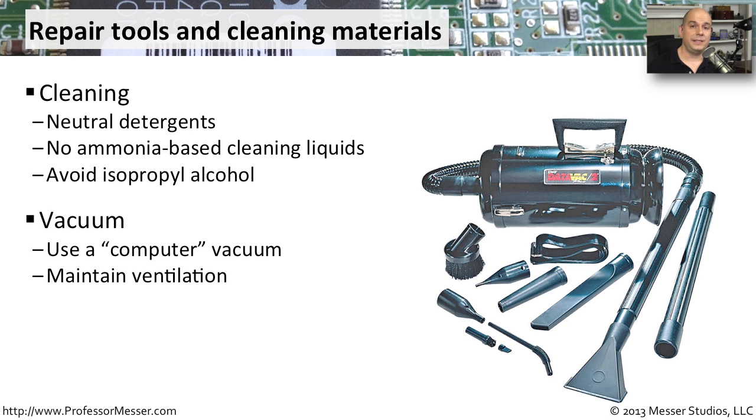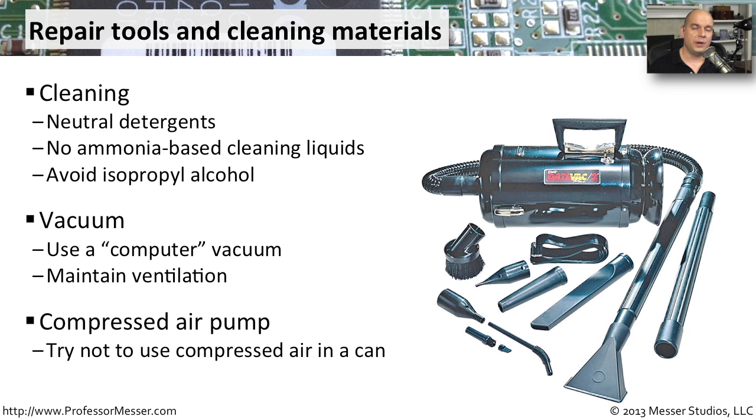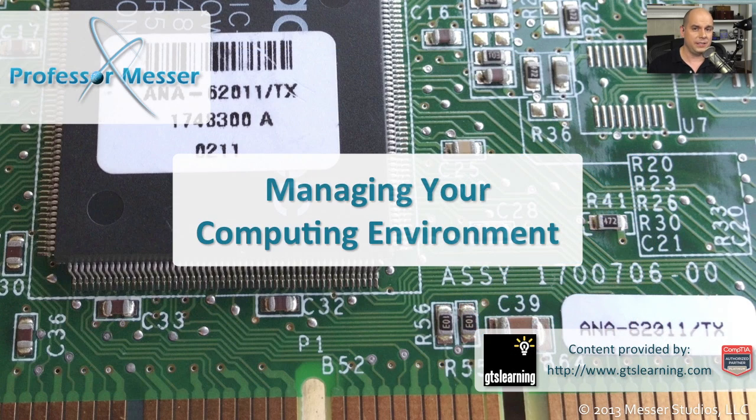Although it may seem that a vacuum cleaner would be a good choice for cleaning out the inside of a computer or the inside of a printer, it may not be the best course of action. That's because as you're sucking up all of that dust, it is creating static electricity on those plastic nozzles that you're using, and you could potentially touch a device inside of your computer and discharge that static electricity. If you must use a vacuum, make sure that it is a vacuum that is designed to be used inside of computer systems. Using compressed air in a can might be good for small jobs, but you want to be sure that you're getting a type of compressed air that is safe for the environment, and you want to be sure that you're not just blowing dust around, that you actually are removing that dust from the device.